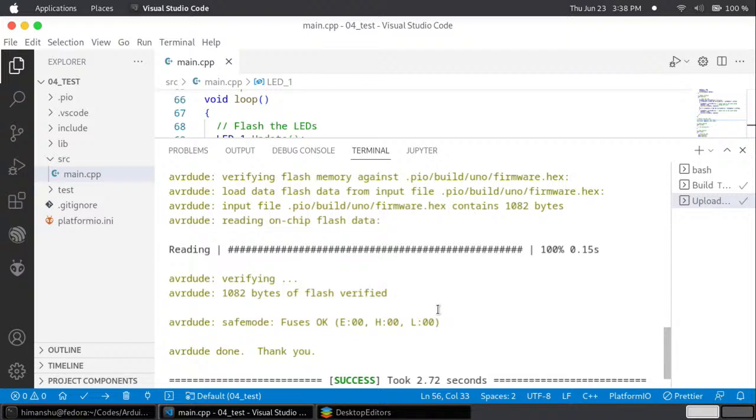And one more thing I want to add to our discussion. If you have any doubt that whatever we are doing with the help of millis, you can do the same thing with the help of delays, then I give you one assignment. Please try it yourself: control 3 servo motors with different rotations and 3 LEDs with different turn on and turn off times altogether, and try to write the code using delays. Then you will easily understand the need for multitasking and how we are performing this multitasking ability with our microcontroller.